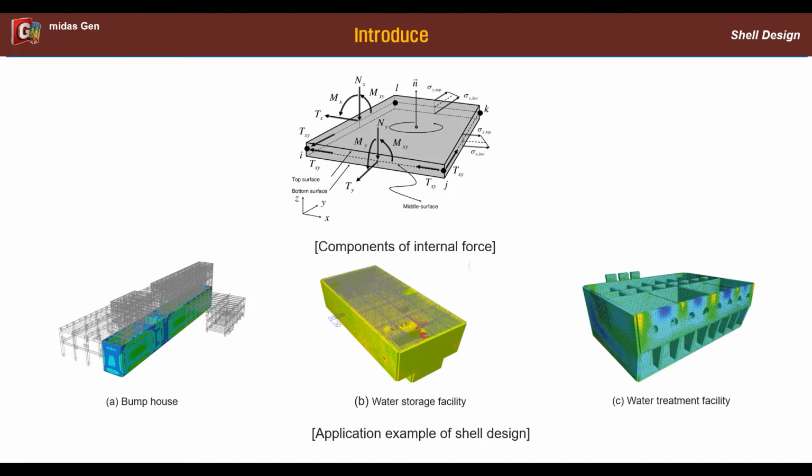In the case of meshed slabs, only out-of-plane moments and shear forces are supported. So we cannot achieve the desired design results when resisting in-plane axial forces and moments due to lateral earth pressure, such as underground slabs. And the meshed wall design is also supporting only moment, axial force and shear of in-plane. However, it does not consider out-of-plane. So we can't get the design result of 2D member that must consider a member force of out-of-plane and in-plane together, like a dome structure.